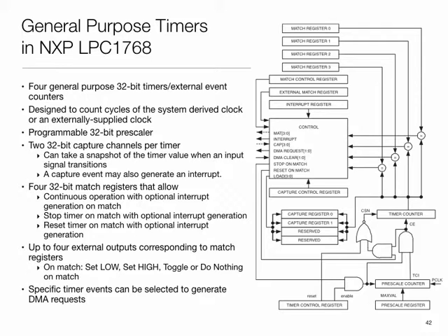And by comparing it against the recent history, I can say whether my clock is running too fast or too slow. And if the clock is running too fast or too slow, then I can apply some correction factor. So I can create some sort of a function which the application calls to ask what time it is. It basically takes the current counter value as well as the corrective factors and generates a modified value so that the application sees a stable time. So one can generate a stable time out of these kind of facilities.